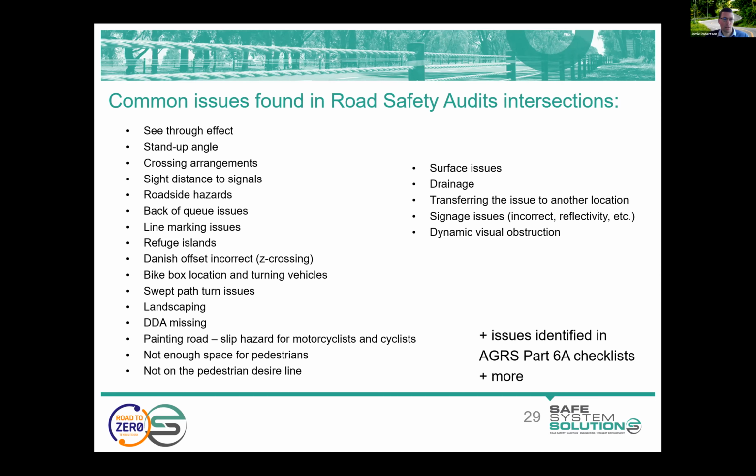Many of these issues at intersections relate to conflicts between vehicles, and also with vulnerable road users, and managing the impact energies at locations where we might encounter pedestrians or cyclists, providing adequate space and sight distance to those users. Obviously, there are increased requirements around drainage and the like at intersections, perhaps some DDA requirements at crossing points.